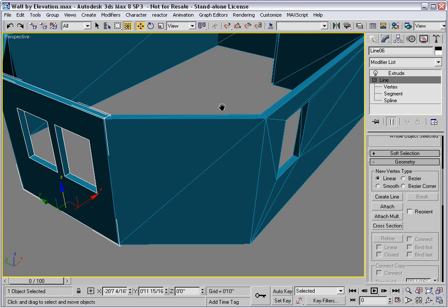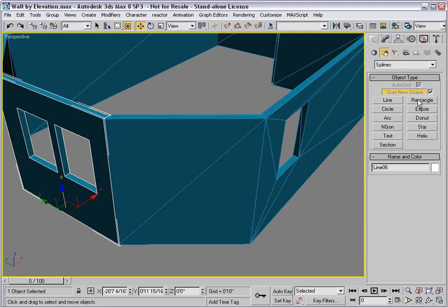On oblique segments, you have to approach openings in a different way. This segment was made by outlining the spline in plan first and then extruding it up. So if we sketch a spline on this particular segment, it would have to be in plan, and that's not going to be helpful to us. So you would approach this kind of segment in a different way.